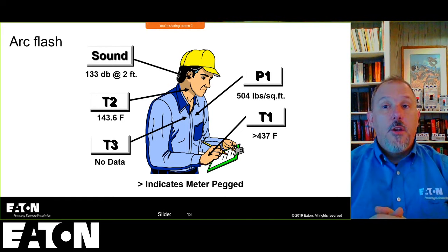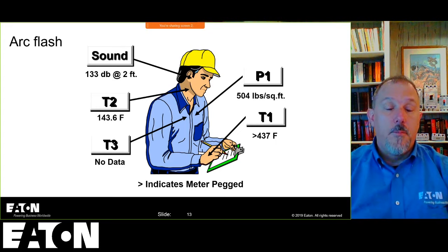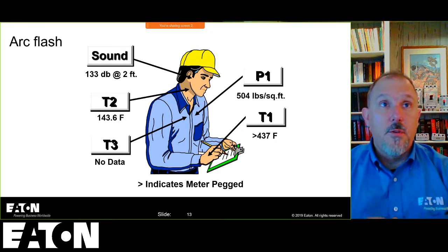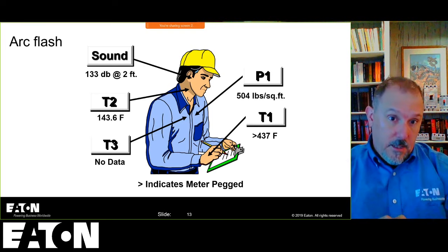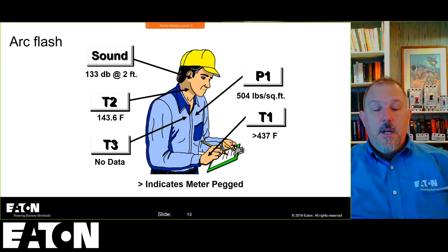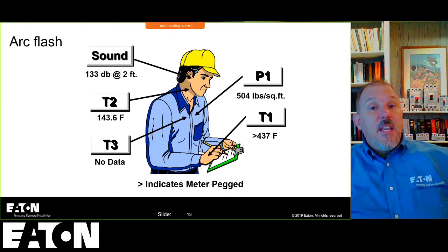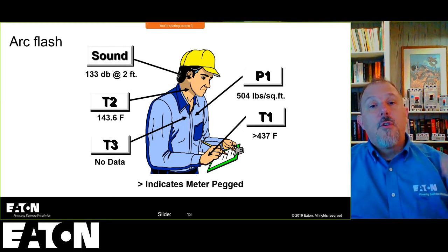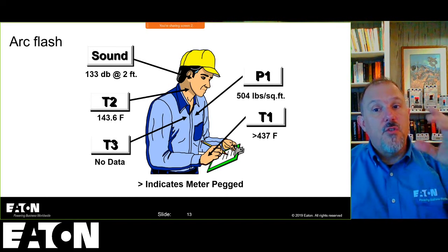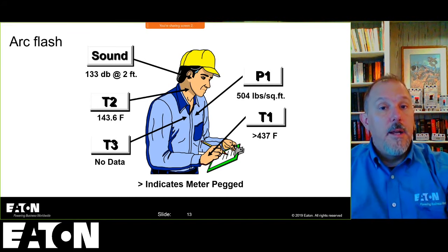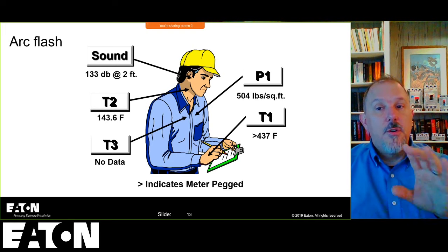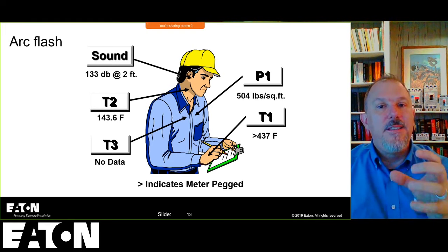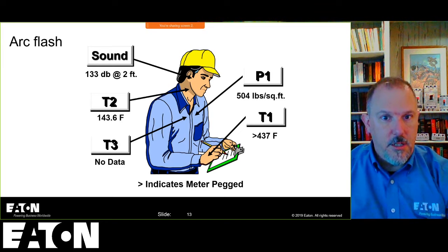I mean, after that goes, you're going to have to go home, probably change your clothes, change your shorts a little bit on that one because it's still an event to behold, but not as catastrophic as the first one. Now on this next event, you're operating, it's a much smaller fuse. It's right there in that enclosure, in the motor starter, and you're going to see what current limitation does for the reduction of arc flash.